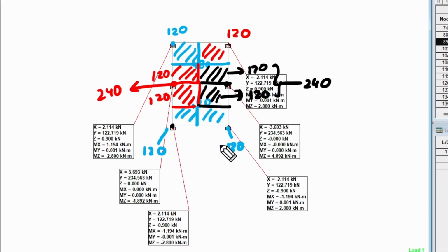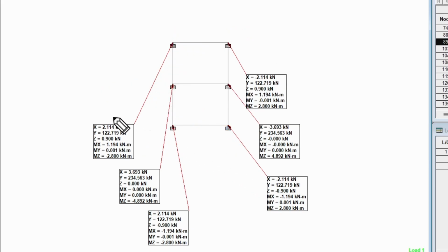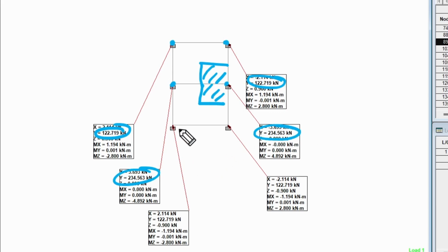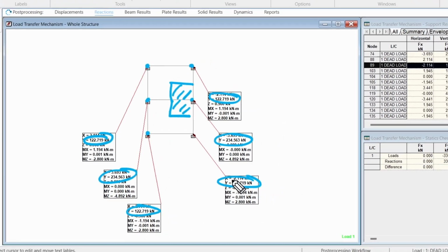Thereby you can very easily see that this floor right here is getting a value close to 120. This node is again getting a value of close to 120. These two, because these are taking this floor and 1/4 of this floor as well, are getting almost double of that value in both of these cases. Again, these ones are taking just the 120 value.